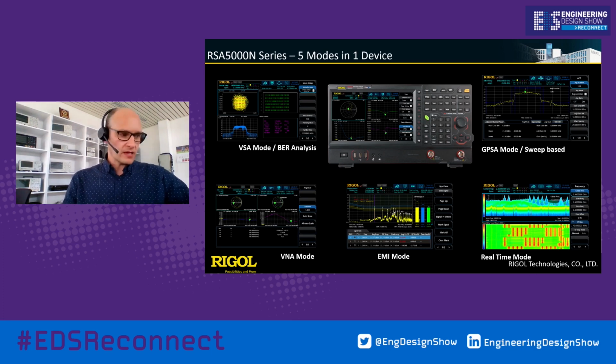We have different modes inside. For example, as I told you before, we have the normal sweep-based spectrum analyzer. We also have the capability to activate the real-time engine with the real-time spectrum analyzer with a real-time bandwidth up to 40 megahertz, which can be used for the whole frequency spectrum up to 6.5 gigahertz. We can use the test device for EMI pre-compliance tests, with an EMI mode inside specific for such tests.